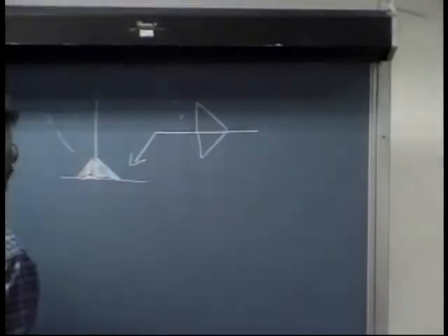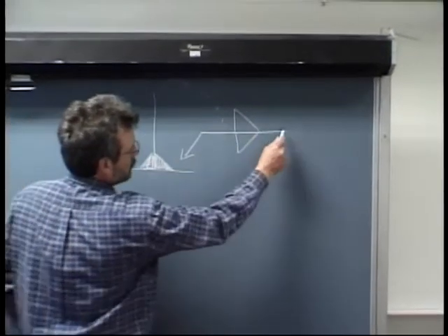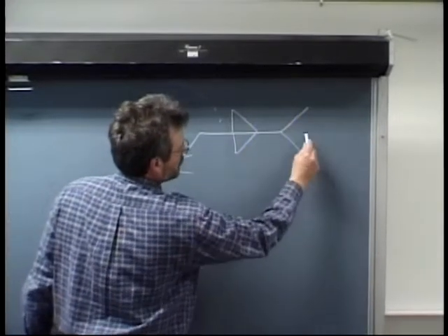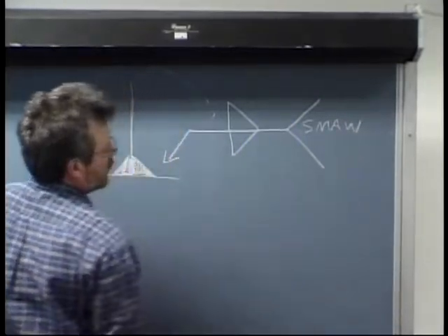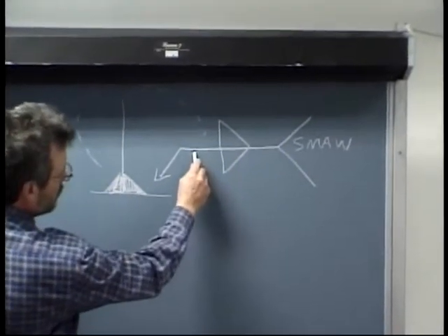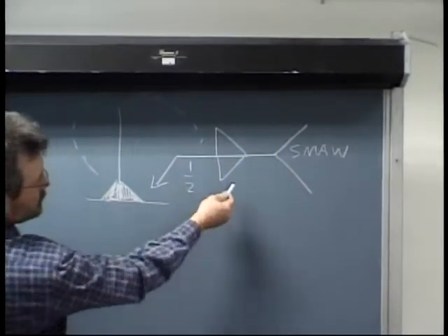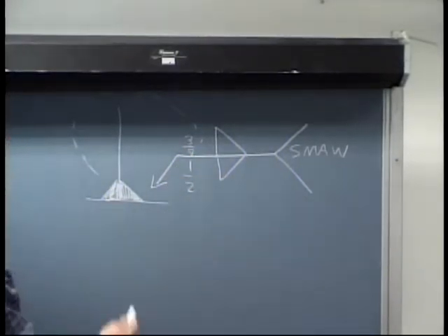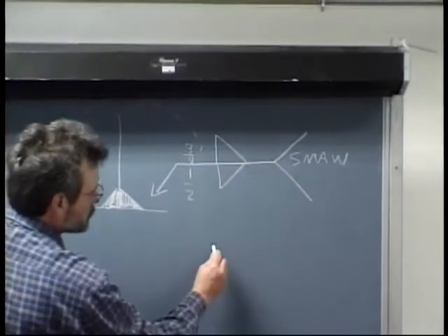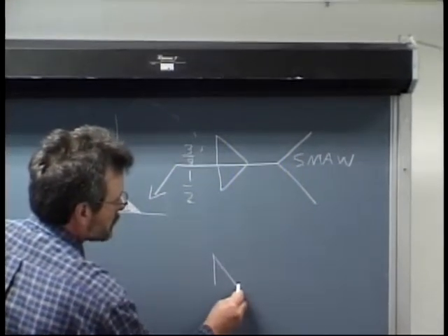here we have a welding symbol, and we'll put a tail on it, and we'll say SMAW. And so this weld symbol might have 1/2 inch for the size of fillet weld there, and 3/8 inch for the size of fillet weld there. So these are all elements of the welding symbol. But the weld symbol that we're using is the symbol for a fillet weld.